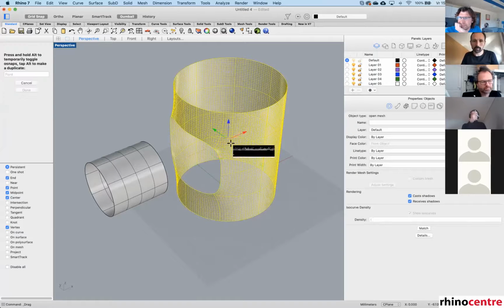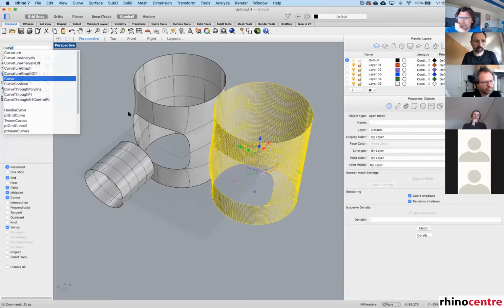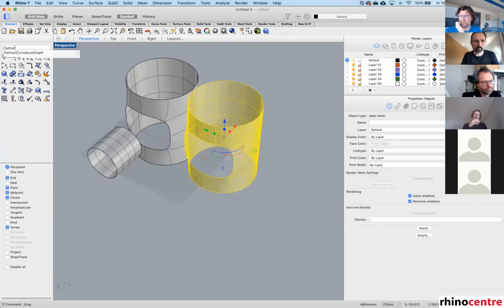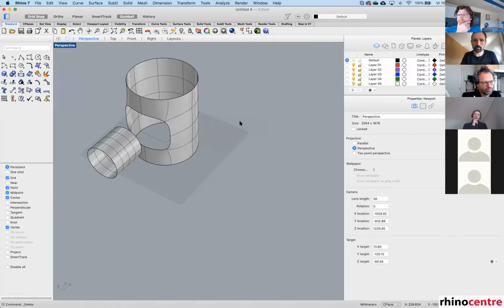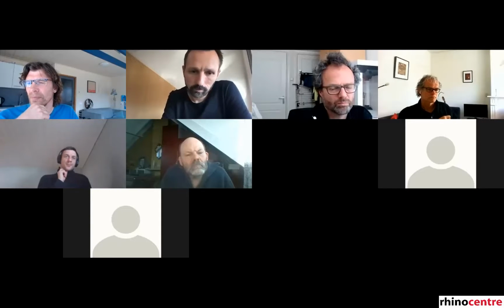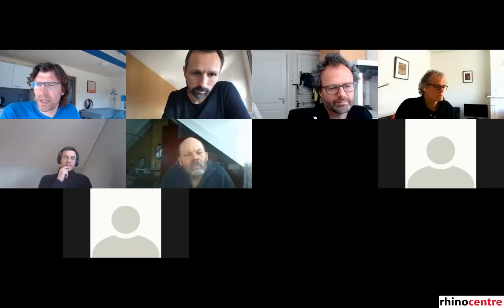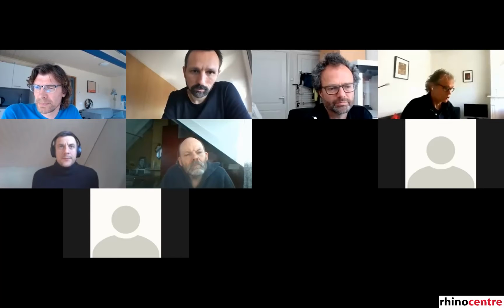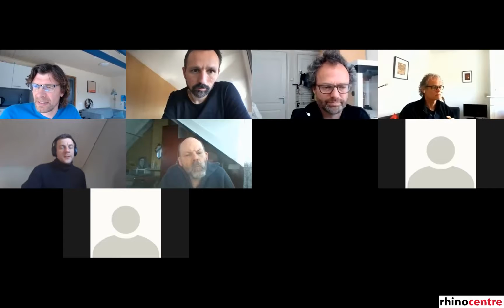I'd just like to add a point to what you said, Gijs. For naval architecture, we work a lot with analysis of the stations and waterlines. But I found somewhere, must have been on Rhino Centre, a Grasshopper model that allows you to do that automatically. Then you can get this analysis done, even with SubD models. You can, for example, make a Grasshopper script and then analyze the lines plan in Grasshopper. Is that what you mean, Nicholas? Yeah, that's exactly it.